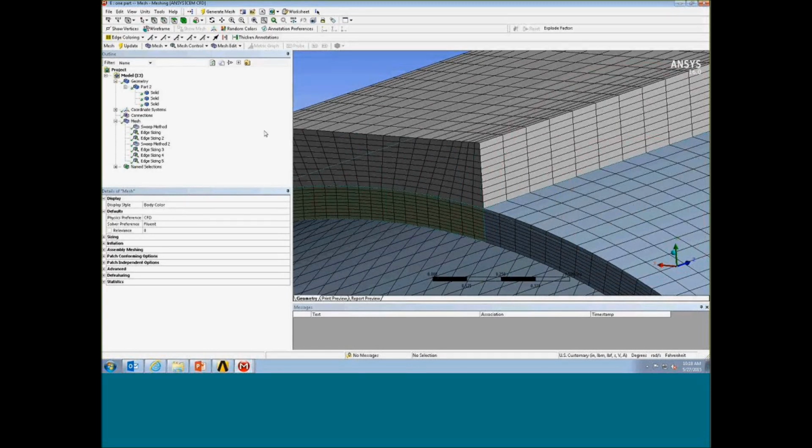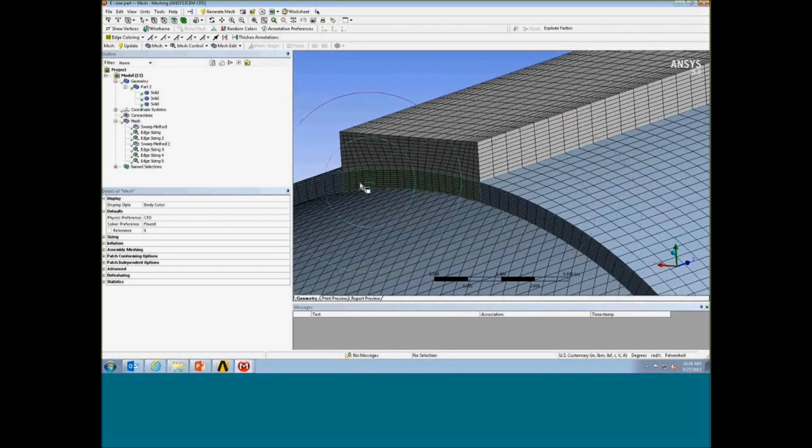And when you bring those into the solver, regardless of Fluent or CFX, they will be recognized as the flow-through mesh. So you don't have to worry about interface problems. So that's one nice thing: you can take advantage of this feature to divide the flow volume into 3 parts and form a new part, so they have conformal elements across the boundary.